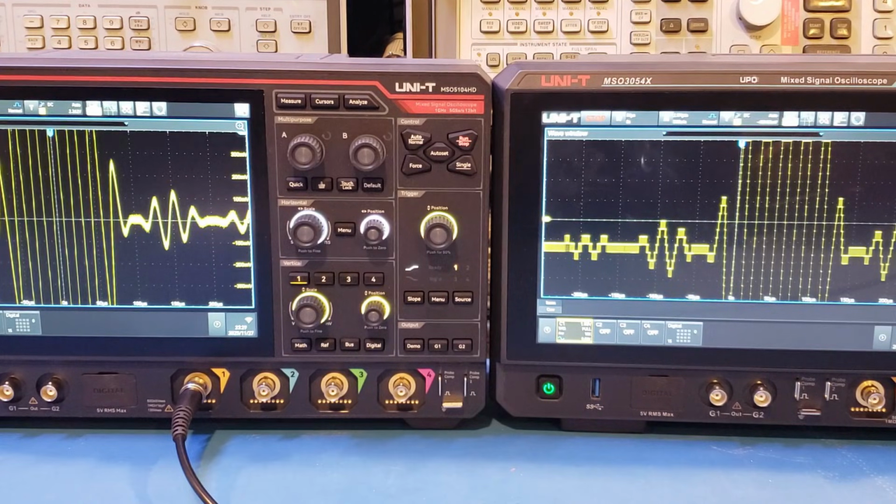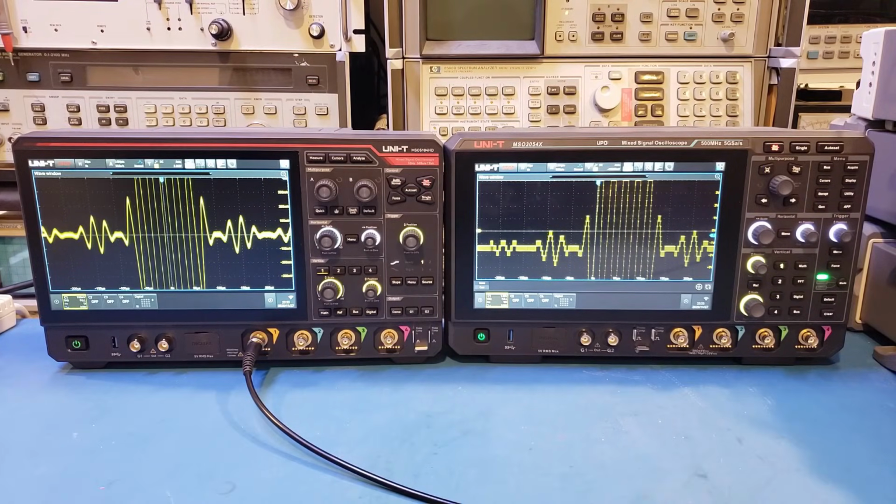So for the same captured signal, we can actually zoom in further and still have good resolution, as you can see here. So now with the same captured signal, you can actually resolve both the higher amplitude portion and the lower amplitude portion in the same shot. This is essentially the higher dynamic range I mentioned earlier. The second benefit of a 12-bit scope, which a lot of reviewers don't really mention, is that it actually has a lower noise floor in FFT mode when doing spectral analysis.